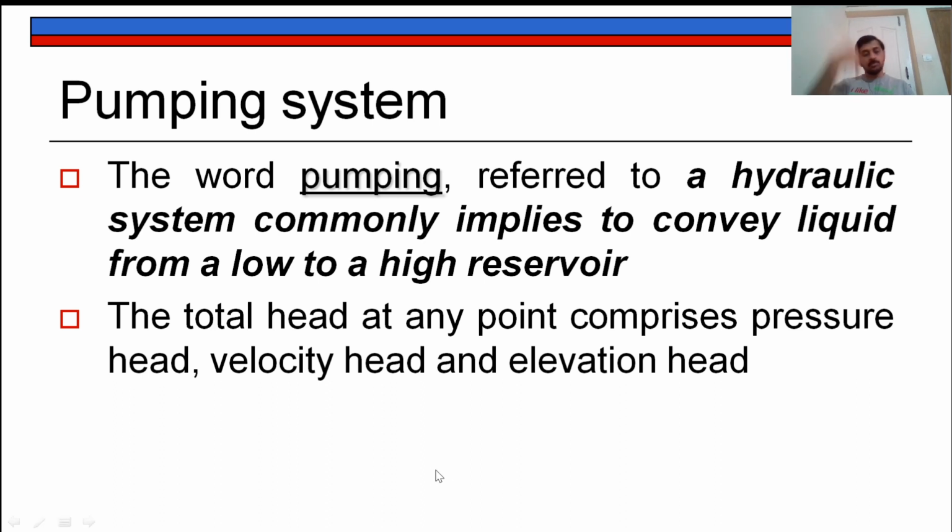because the opposite will happen automatically under the effect of gravity. From a higher level to a lower level, we do not need to employ a pump. We don't need to consume energy for that. By default, the fluid will flow under the effect of gravity. The total head at any point comprises pressure head, velocity head, and elevation head. These three are the important heads at any point in a pumping system.